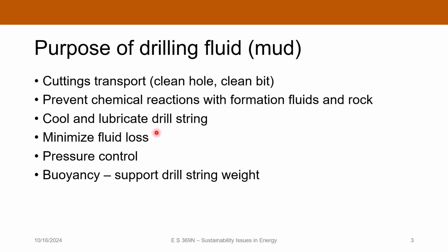You need to minimize the leakage of fluid into the formation. We call that fluid loss. And then they control the pressure downhole, which is also an important thing to do. And finally, they impart some type of buoyancy where they support the weight of the drill string and help minimize the stress that's on the top drive.